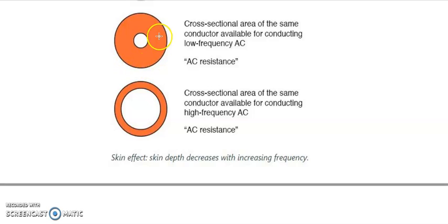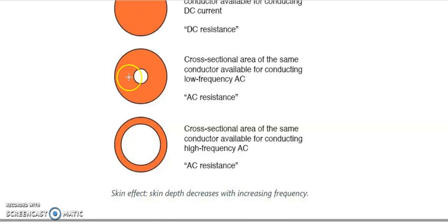Once the frequency of the rotor decreases, the effective area of cross section will increase. If it increases, the resistance offered by the conductor will also decrease. Thus, current will start to flow uniformly throughout the conductor. Slowly, the slip will again be around 1% finally.